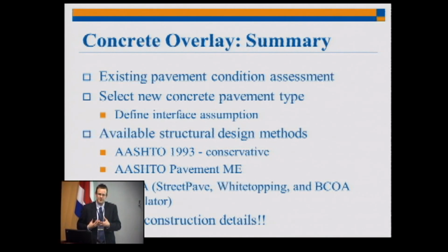Kind of in summary, I primarily talked about bonded concrete overlays of asphalt, but the key here again is assessing the condition, so picking bonded versus unbonded, and then finding the structural design method, which may not be that easy, so I recommend going to some of those publications and really reading very carefully which method works. The AASHTO 93 method may or may not work. I would be very nervous using that because there are a lot better tools out there right now.